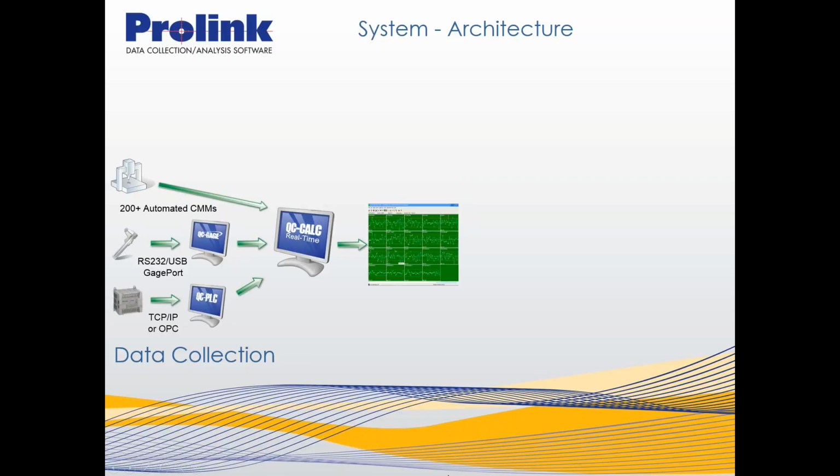There is another module called QC PLC on the data collection side, and this piece of software is designed primarily to connect via TCP/IP Ethernet connection to a PLC in a machine and operate a controller or a robot or something like that that has process information that you're interested in gathering and charting, or even merging together with measurement data for correlation purposes.